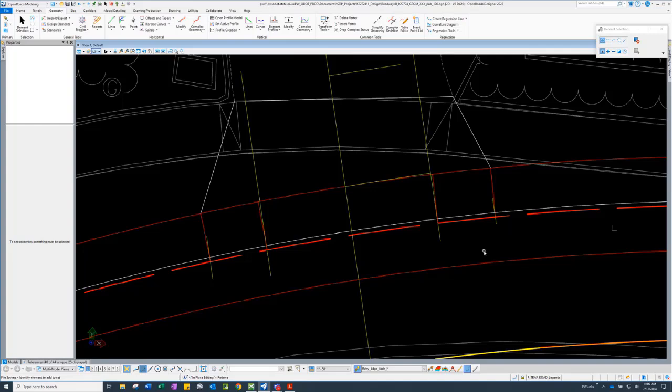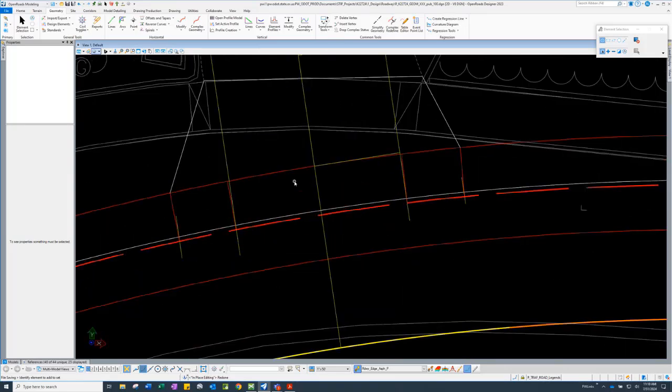Okay, thank you. So yeah, the advantage of this is when you run a corridor and you reference in this geometry, this is further down, we'll show this a little more. You can snap to these brake lines and the corridor will follow this as well. So you move this driveway in your geometry file, the corridor file will update.